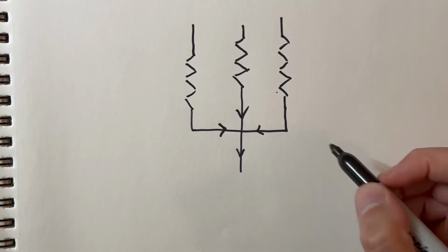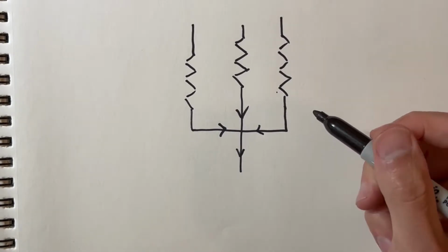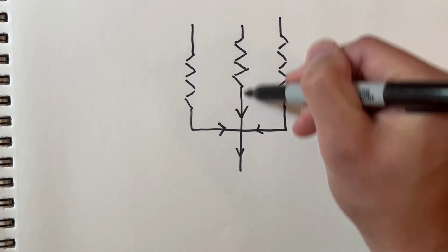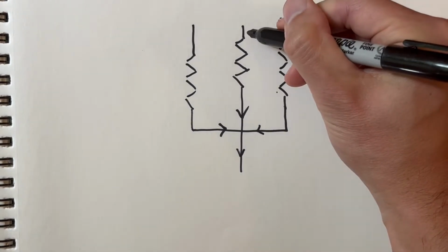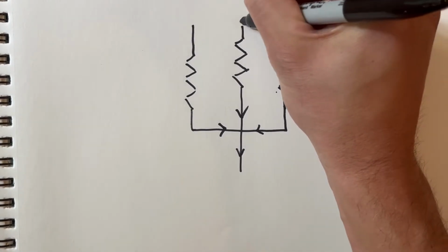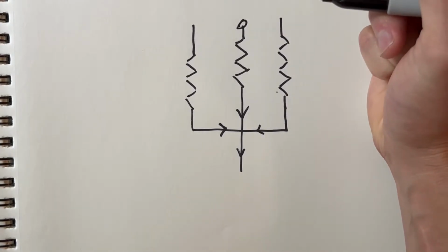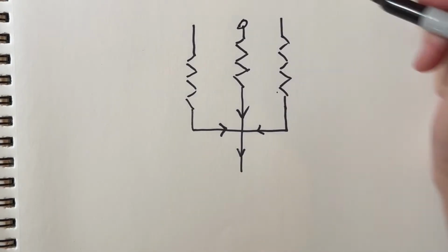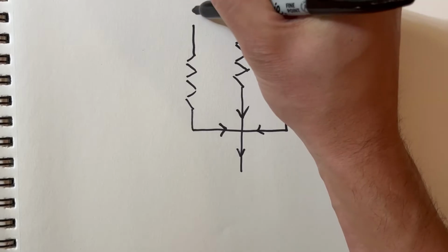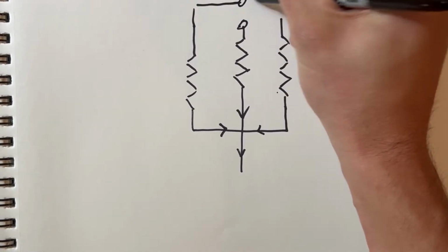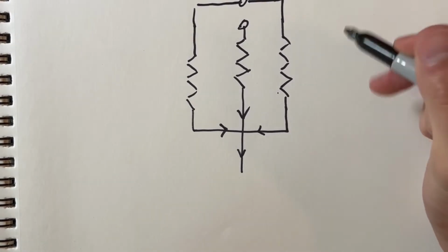Now we need to think about how we are going to actually get our fluid into this device. We'll represent a tube fitting with a circle that comes in the middle of the channel there. Then for the oil outlets, we'll just tie those together to their own tube fitting at the top of the device. And finally, we just need to collect our droplets from the outlet channel with another fitting.